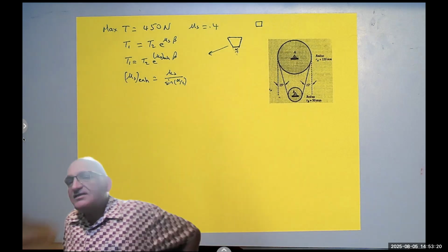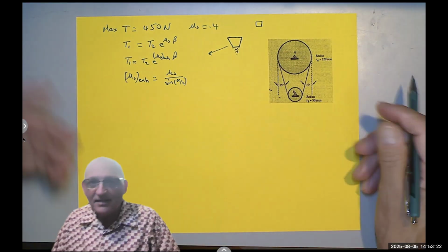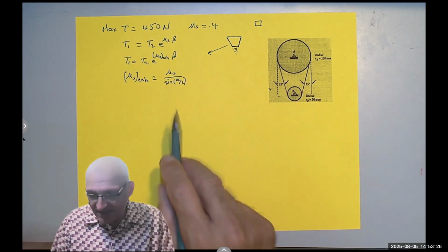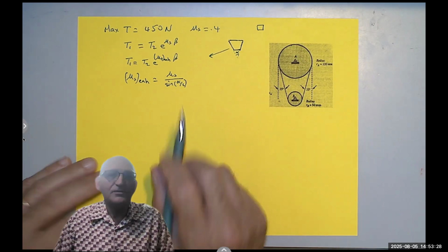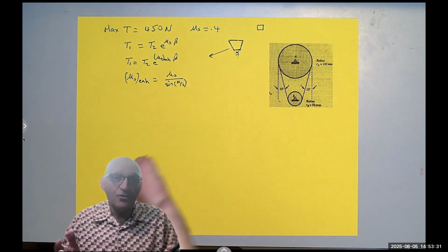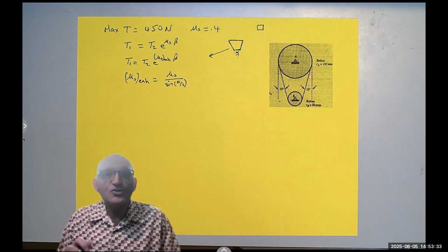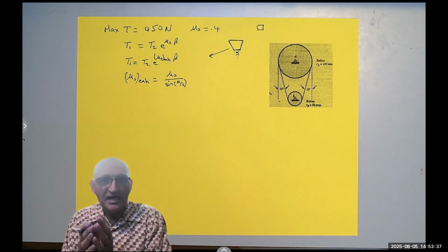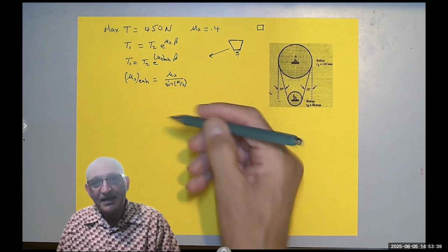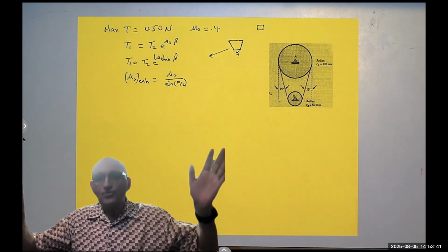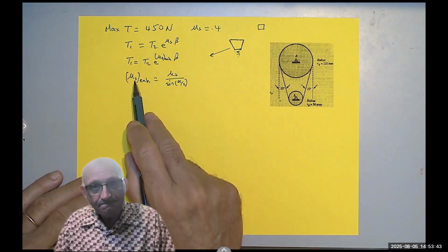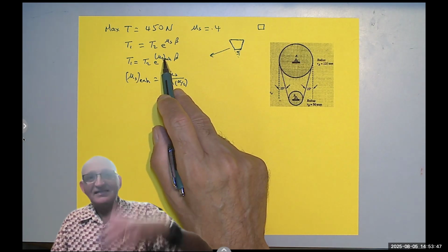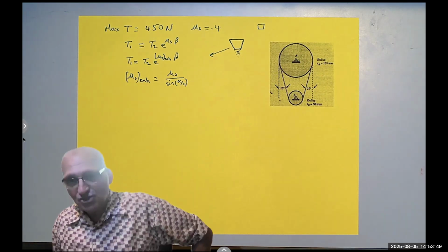So it tells you this is a 10-degree belt or 18-degree belt. They give you the alpha. And you can see that the sine value is less than 1, right? And the smaller the angle, the smaller the value of sine alpha over 2. So when you divide by a small number, it increases mu sub s. And when you put it as an exponent to e, that makes it much larger.